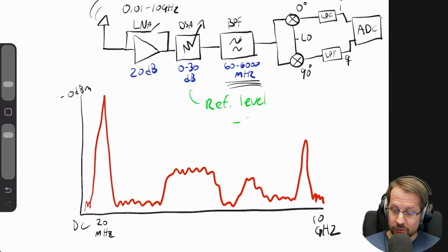So when you set the reference level to 0.0 dBm, you have the fullest amount of attenuation, and then you slowly go down, right, to -10 dBm. You move down, and if you start to see harmonics, or you start to see some sort of signals that just don't look right, you change it up again, right? So you use the reference level up and down, right?